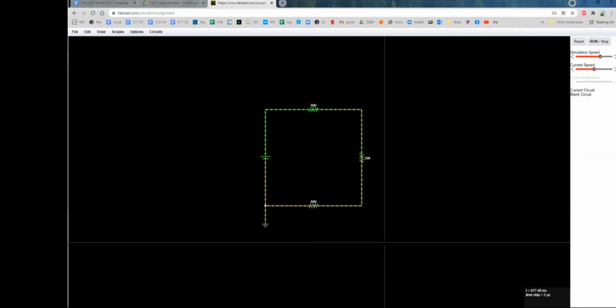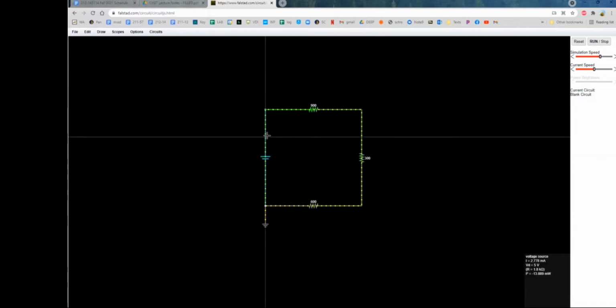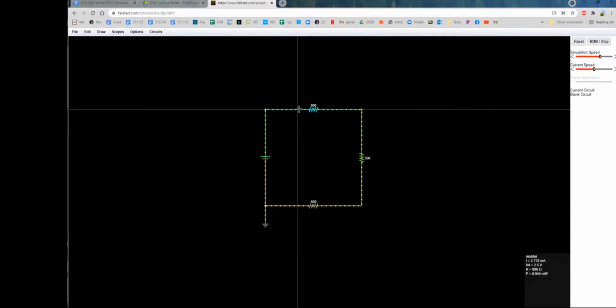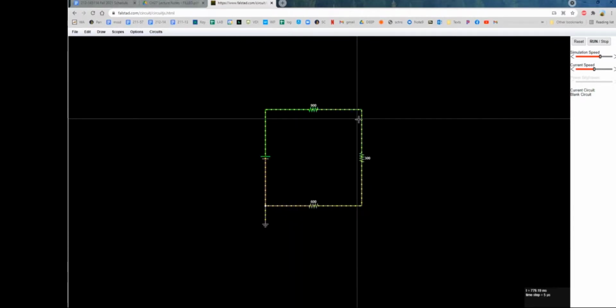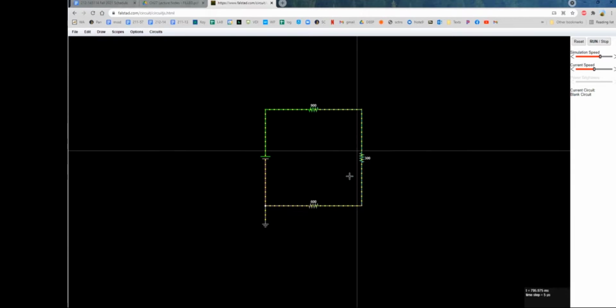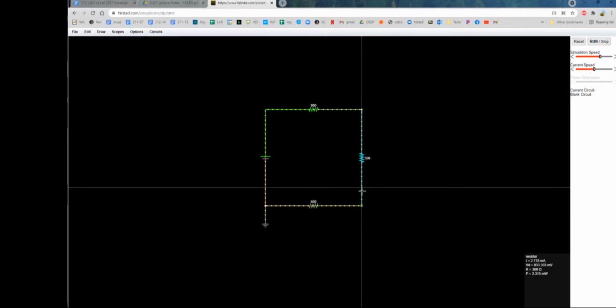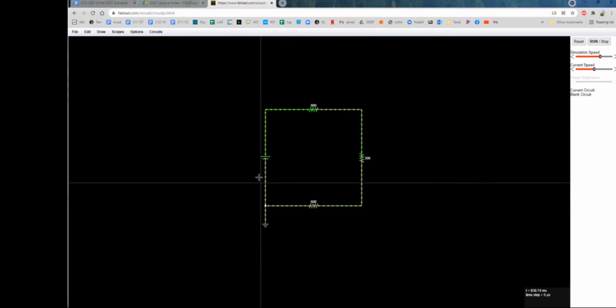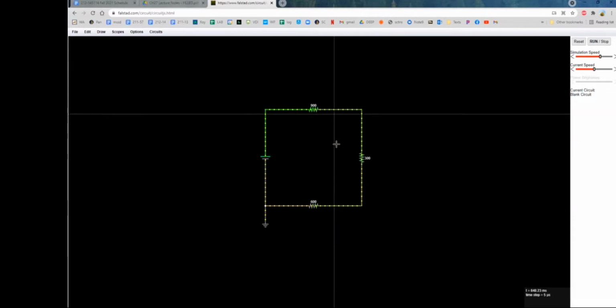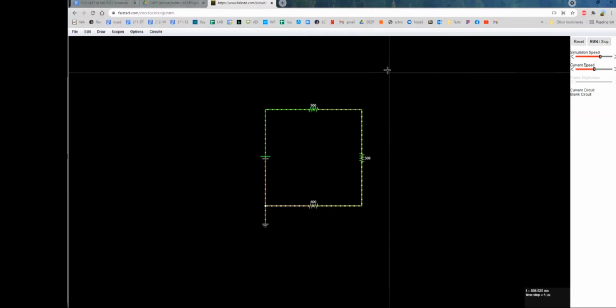I know this is a simple series circuit. So I know that the current everywhere is going to be the same, 2.778 milliamps. It's the same everywhere. So that's the sanity check. That's the sanity check to ask and answer the question, is this a series circuit? And it is a series circuit because the current's the same everywhere. And obviously you can look at it.